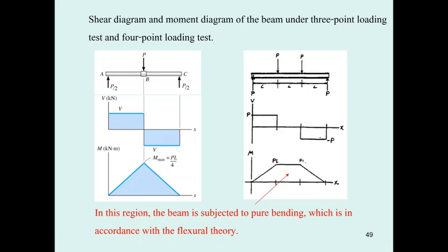I also assign you to go back and review your statics to draw the shear diagram and moment diagram of the 3-point loading and 4-point loading. I should note that this region of 4-point loading is important because it's the stage of pure bending, which is good if you prefer to study the behavior of the material only in pure bending. That will be in accordance with the flexural theory.